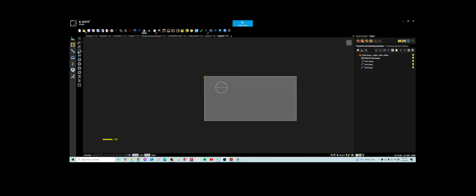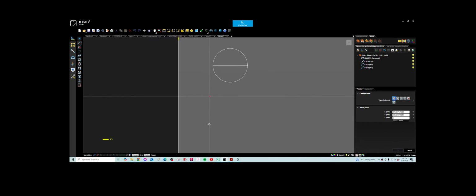So this is done. Let's talk about polylines now. Polylines are a very good way to follow something. When you press the line, you always have to go and find the previous point. With the polyline, it's a continuous line. So you press here, and this will follow.